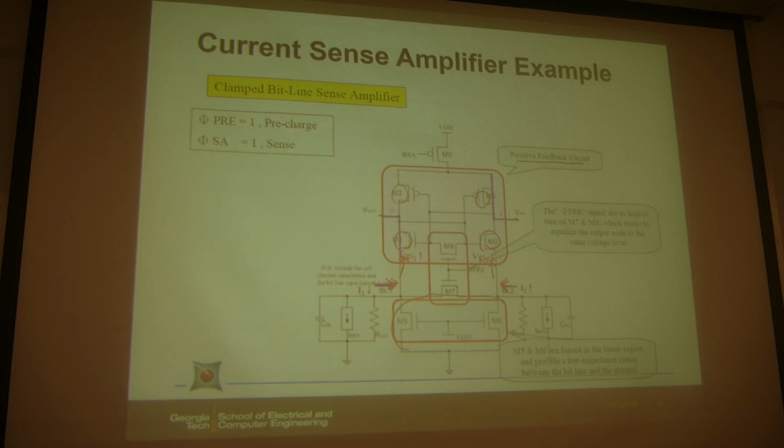So if you recall your analog circuit, of course this is not a small AC signal with a sinusoidal wave, but still it's kind of a small signal. It's not repeated like the sinusoidal wave, but still it's a small current into that. You can use that concept, the input resistance is very small from the source side of the transistor. So that's why this is the current mode.